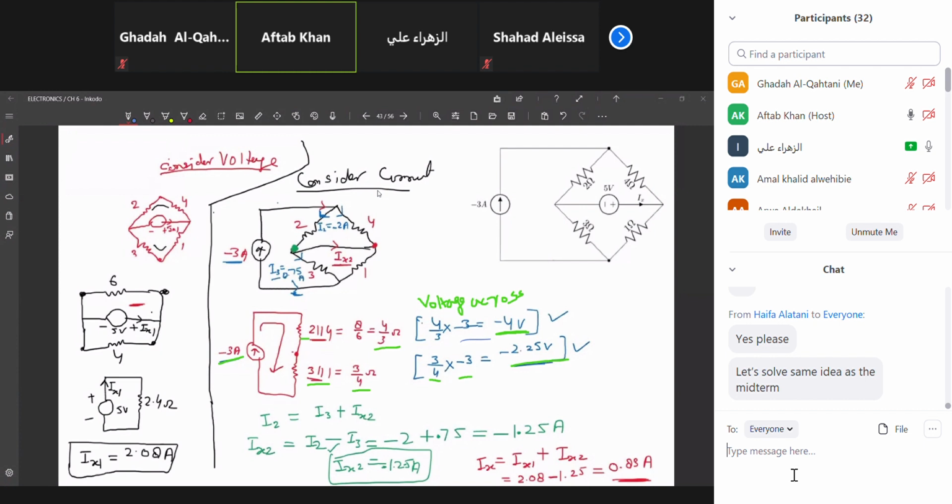As I explained to you, this is the parallel combination voltage. So it means that the same -4 will appear across this one, same -4 will appear across this one, because they are in parallel. Correct? Did you get the point now? Yeah. Okay, so we can calculate how much is the current here also. How can we calculate the current? I know the voltage, which is -4 volts. If I divide by this resistance value, which is 2, then -4 divided by 2 will give me -2 ampere. So I just calculate it. I am not focusing here because I am interested to know this one. Then I go for this one.